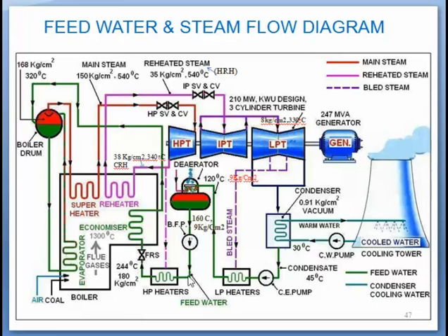After this pumping, the feed water goes through two HP heaters. The heating media for the HP heaters are the bled steam, one that comes from the IP and one that comes from the HP turbine. One thing to remember is that in the LP heater and HP heater, the heating is only sensible heating. It means there is only a change in temperature; the phase will remain liquid only.